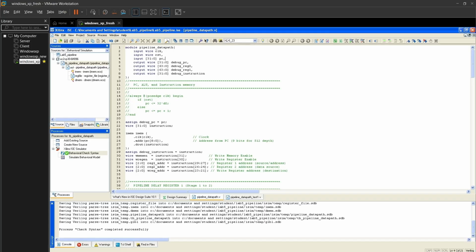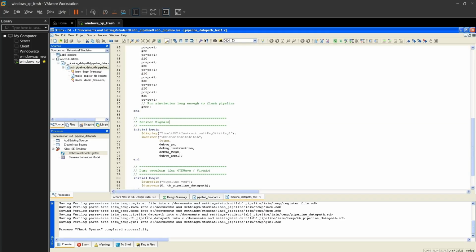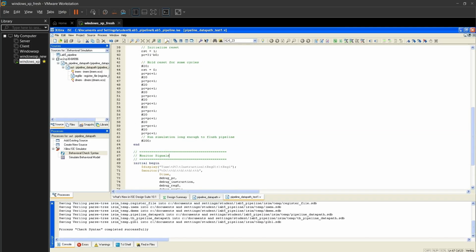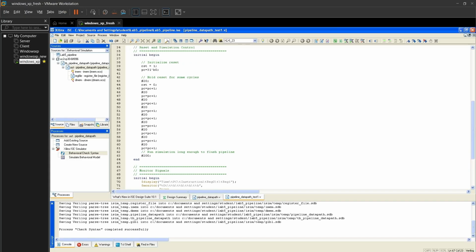Instead of automatic incrementation of PC every clock cycle, we just have an input for PC and made modifications around that. I'll show you the test bench code for that also. In simulation, we're just incrementing the PC at fixed intervals, and in our NetFPGA implementation, we'll just do reg write for all the PC values. So I'll do a small sim for this condition.